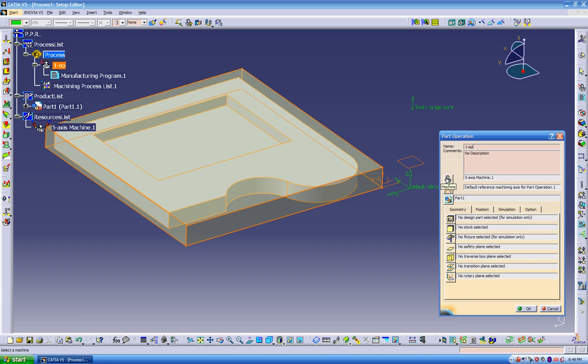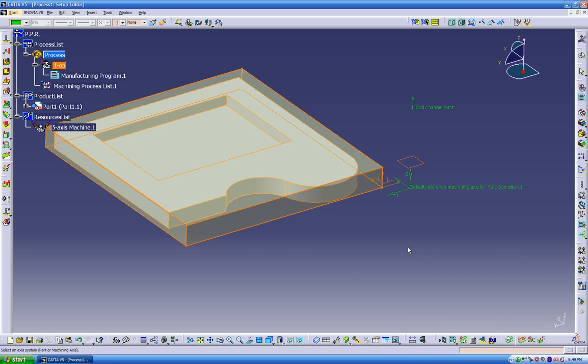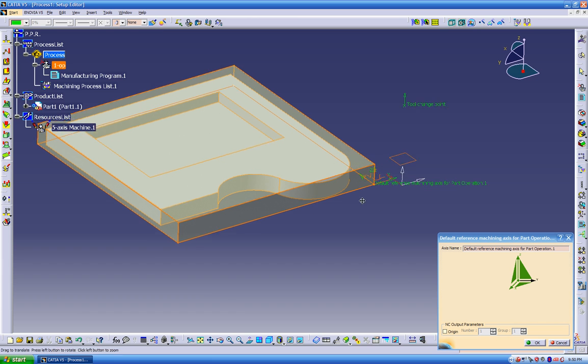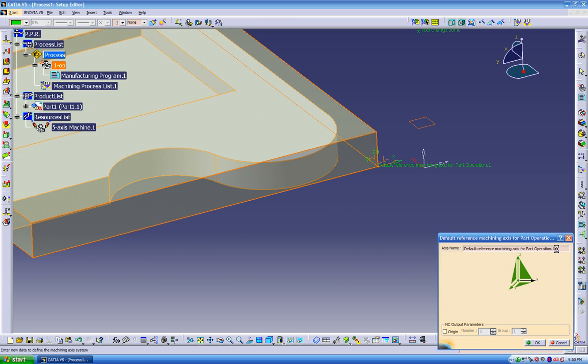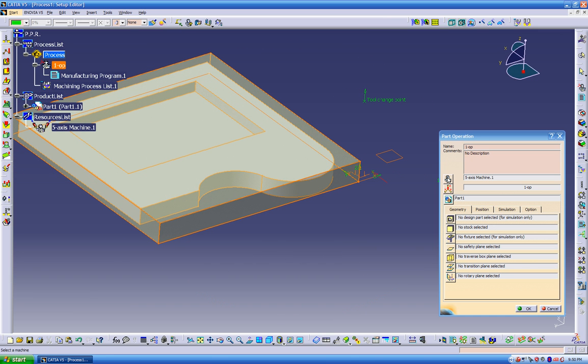That was our machine. Now the second icon is our axis. So we're going to click on the axis. We can click anywhere on the red area, and it's going to ask us, on the bottom over here, to select an axis system. So I'm just going to select this axis and automatically snap into the new position, and I'm just going to call it first stop. So this is our first op axis. So we define the machine, we define the axis.